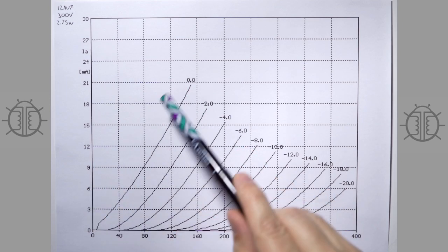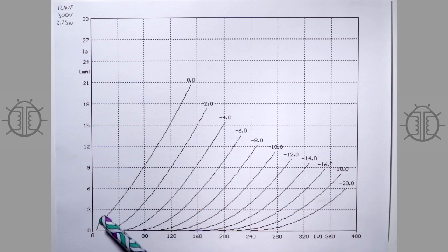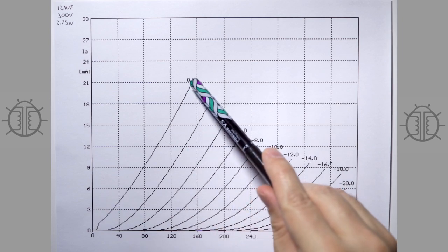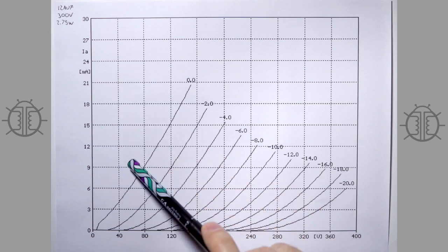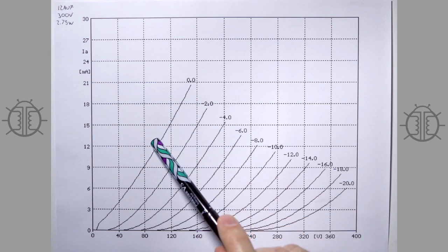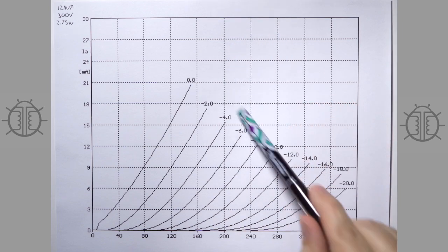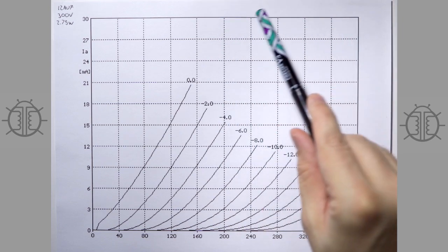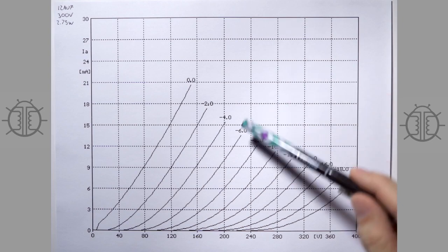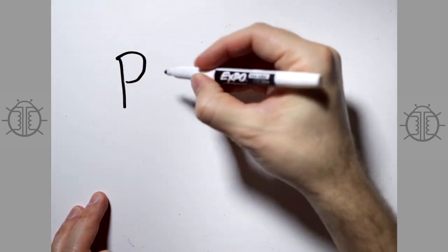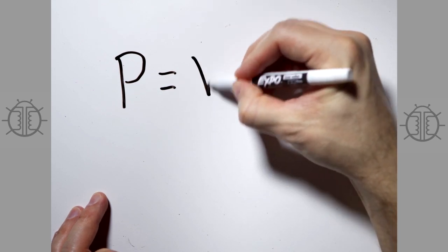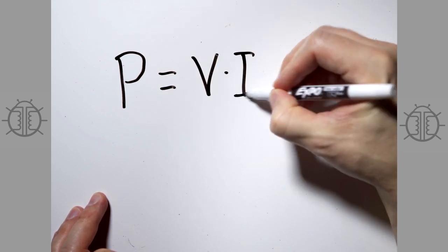Now that's not always the case. Some tubes are designed to operate in this area, but it also requires sort of a specialized driver stage. So for all useful purposes today, this area is inaccessible to us, the positive of 0 volts. And up here, this is beyond the dissipation rating of the tube. These potentially just continue on up here like this, but you know, or maybe you don't know, but power, that's in watts, is equal to volts times amps.